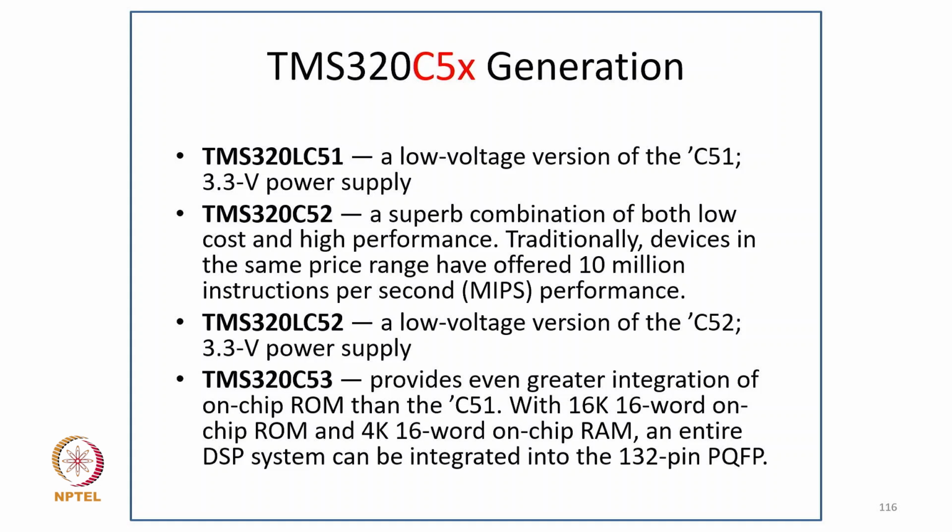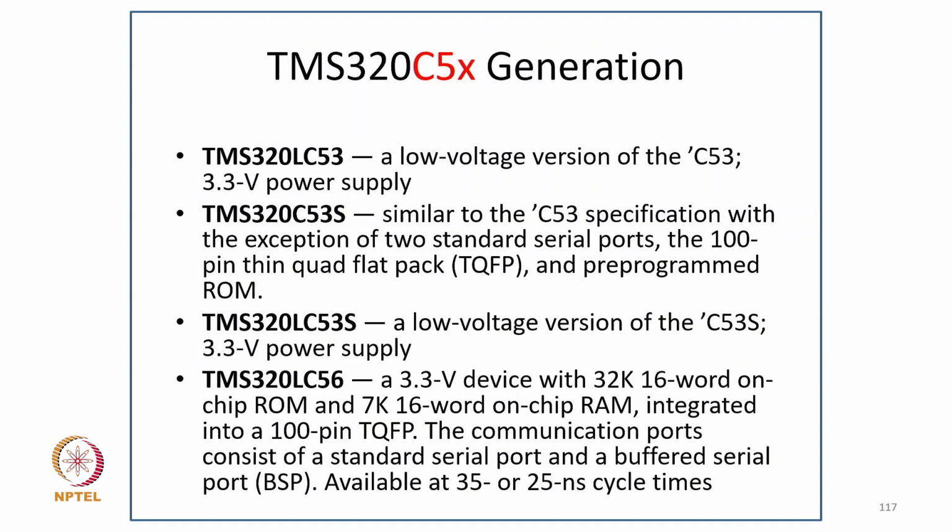even greater integration of on-chip ROM than the C51, with a 16K 16-bit on-chip ROM and 4K 16-bit on-chip RAM. An entire DSP system can be integrated into a 132-pin PQFP. So TMS320LC53, a low cost version of the C53 with a 3.3 volt power supply, and